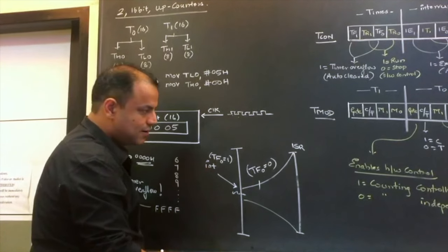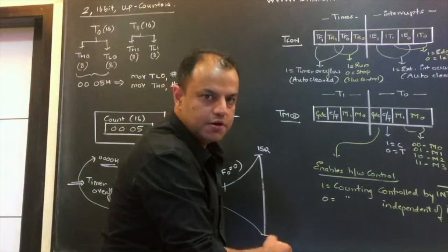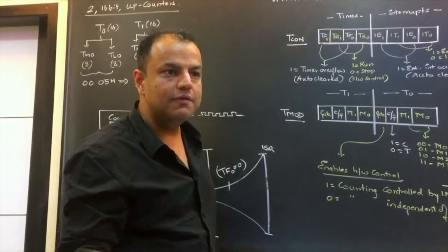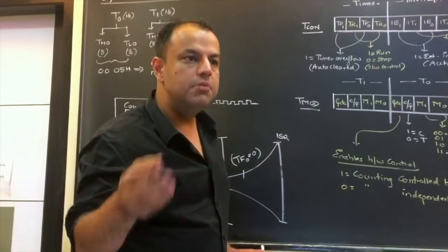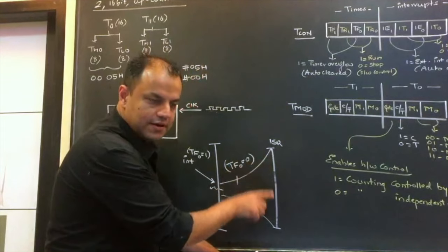It will suspend the current program and go to the ISR, where it will do whatever it wanted to do after the delay. Maybe after the delay you want to fire a missile, maybe you want to launch a rocket, maybe you want to start some shower. Whatever you want to do after the delay, you do over here in the ISR.